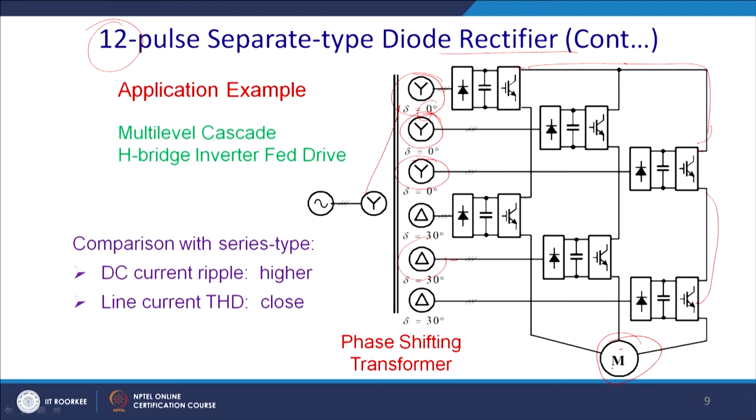out the effective harmonic and it will give you a good quality drive, and this is generally the way of feeding a multi-level. These are all cascade multi-level inverter topologies. These are all the inverter blocks. This is one inverter block, one other inverter block. They have put them in series to build up the voltage. In that way, you can use them.